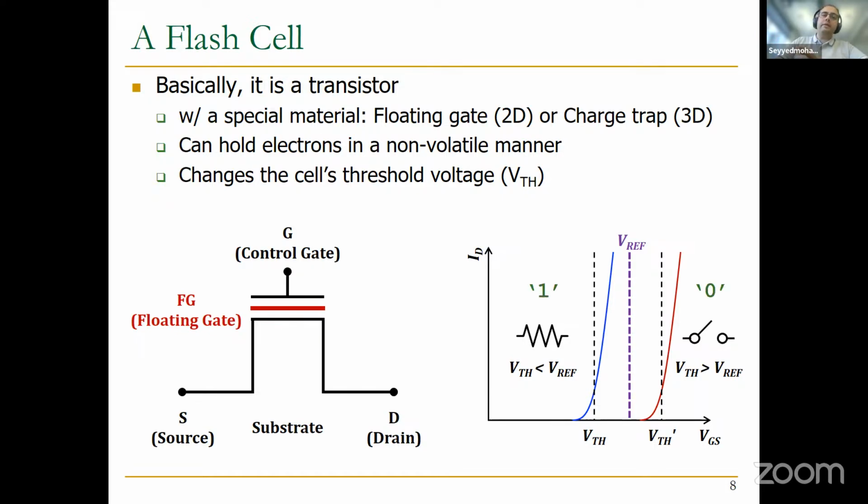So with that, you can easily understand the threshold voltage status in your flash cell. And we can encode that status as 1 and 0. When the threshold voltage is the nominal one, you can encode it as 1. And when it's the high one, you can encode it as 0. But as I also said in the previous meeting, and we will see also today, we can actually categorize this threshold window with more accuracy. So you can consider 2 bits or 3 bits or 4 bits, which we're going to see soon.